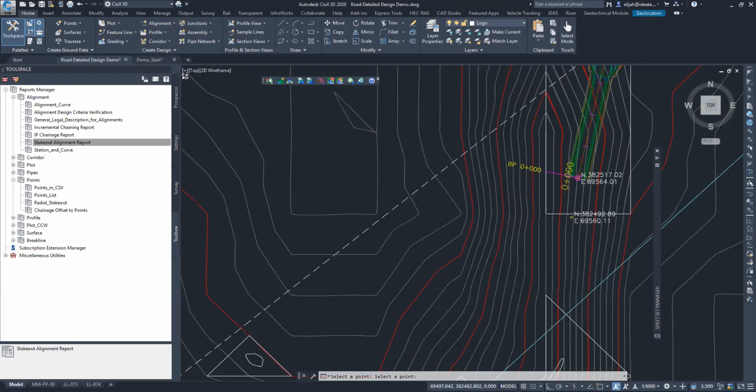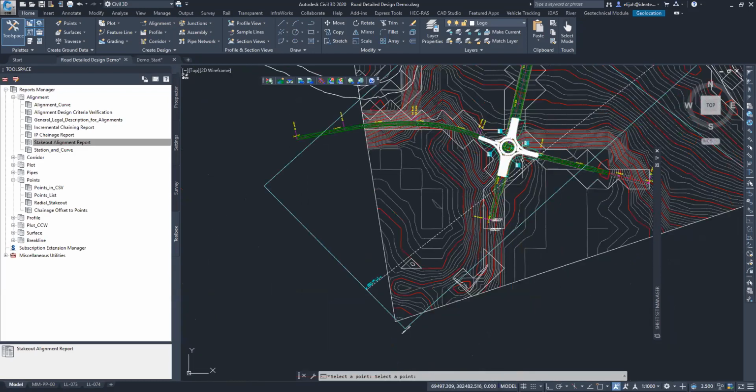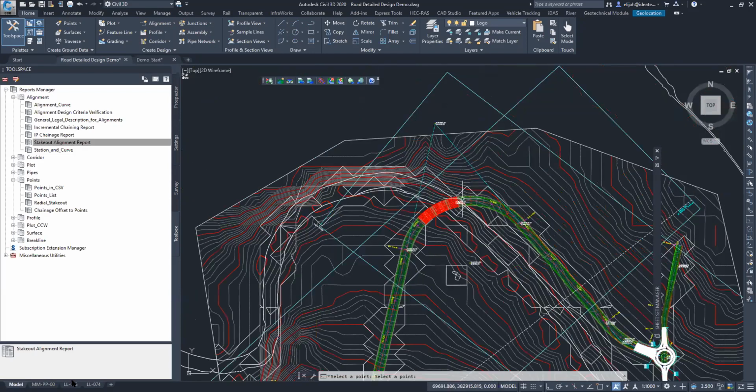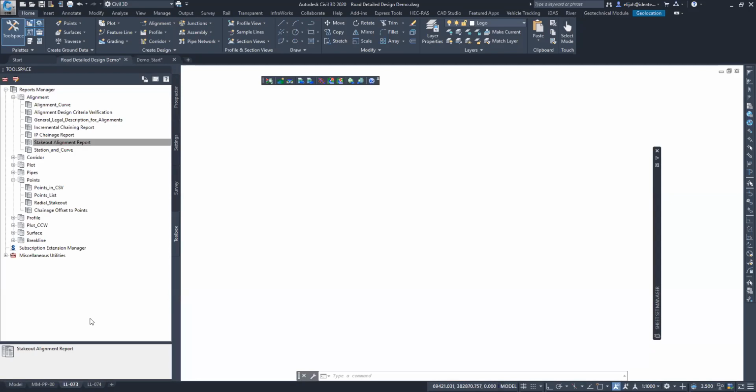Once I've done that, I also need to share this drawing with the team. I want to illustrate the process, but you need to first convert it into a printable format, that is the creation of sheets. You need to produce plan and profile sheets, section sheets, the earthwork volume reports, and what have you, in sheets that can easily be viewed, queried and reviewed by the entire design team. I will illustrate the ones which I've already done before because the time won't allow that.